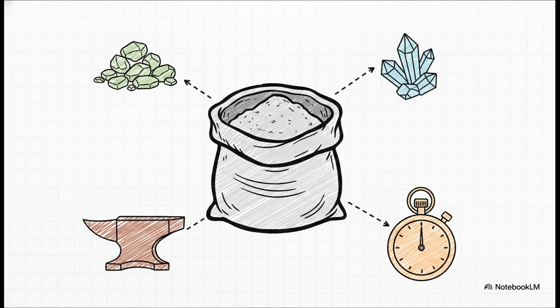Next up, let's talk about cement. Cement is your vital binding agent, and its actual performance relies strictly on a very precise chemical recipe. The chemical benefits of lime, which makes up about 60 to 67% of ordinary Portland cement, are completely responsible for the mix's strength and soundness.